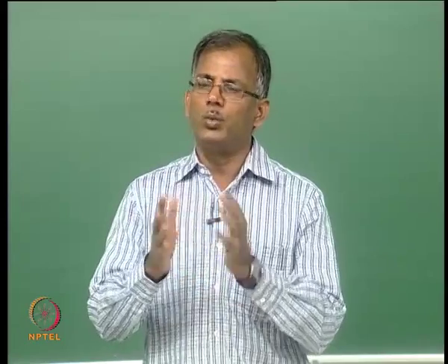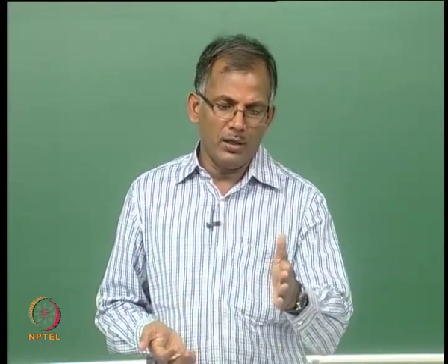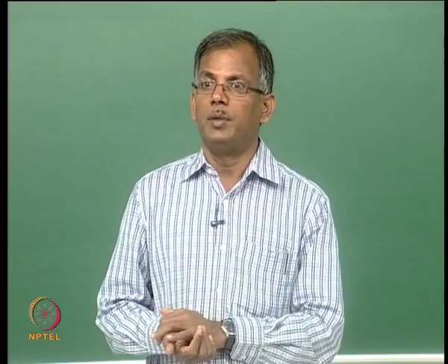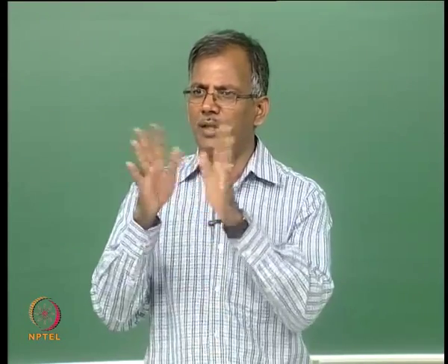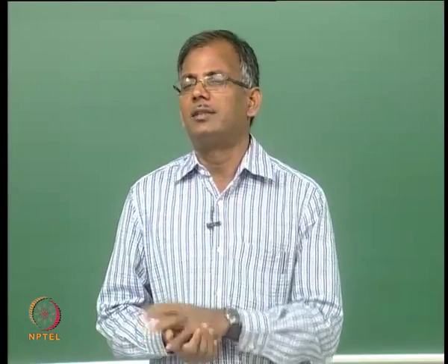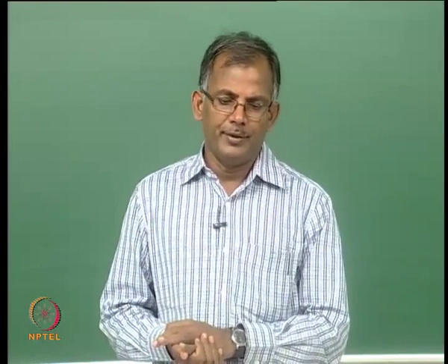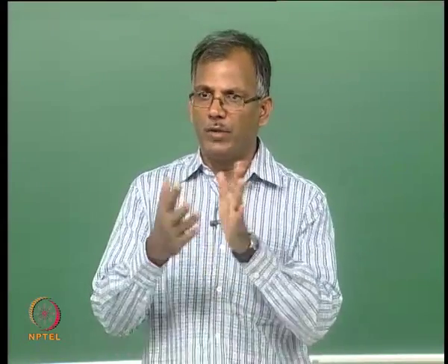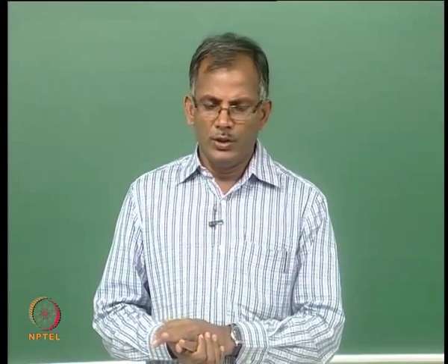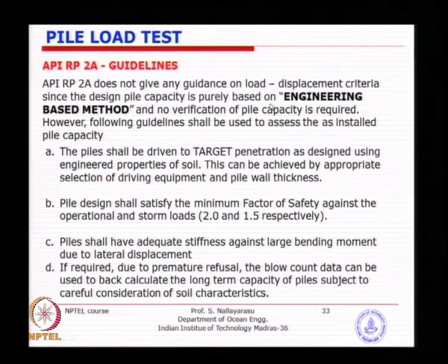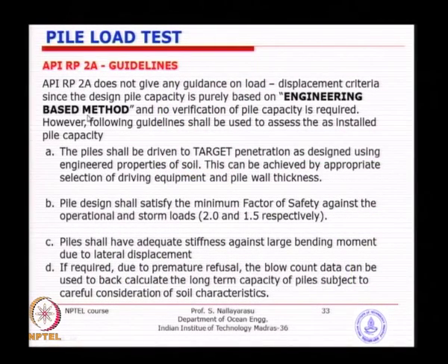So, that is one of the reasons why most of these concrete codes restrict the displacement to smaller values, whereas the offshore structures we never build using concrete, except the concrete gravity platforms. All the fixed type of structures are built with steel material, which has higher tensile capacity and also has ductile characteristics. So, for that reason we go by the method of engineering based design based on soil properties with adequate factor of safety, and we leave it there. We do not want to apply restricting displacement.